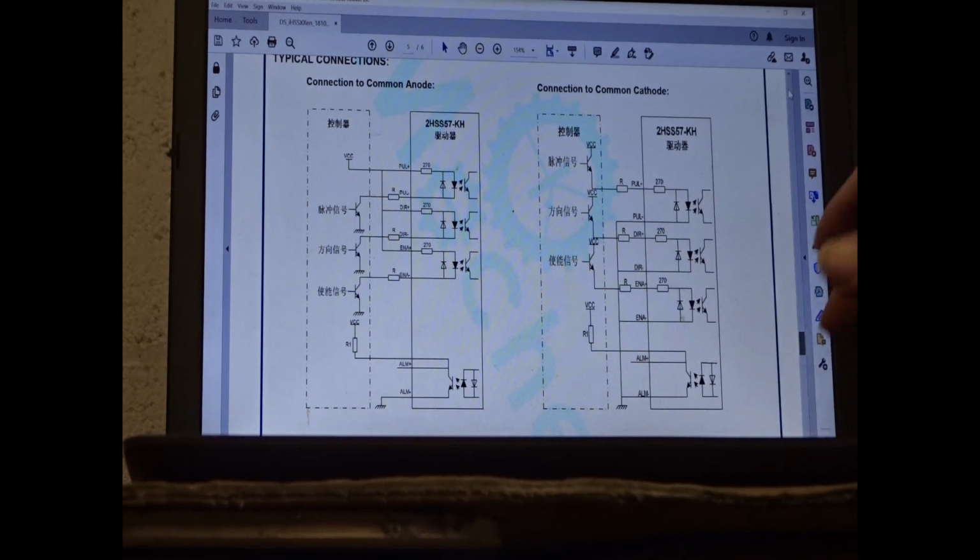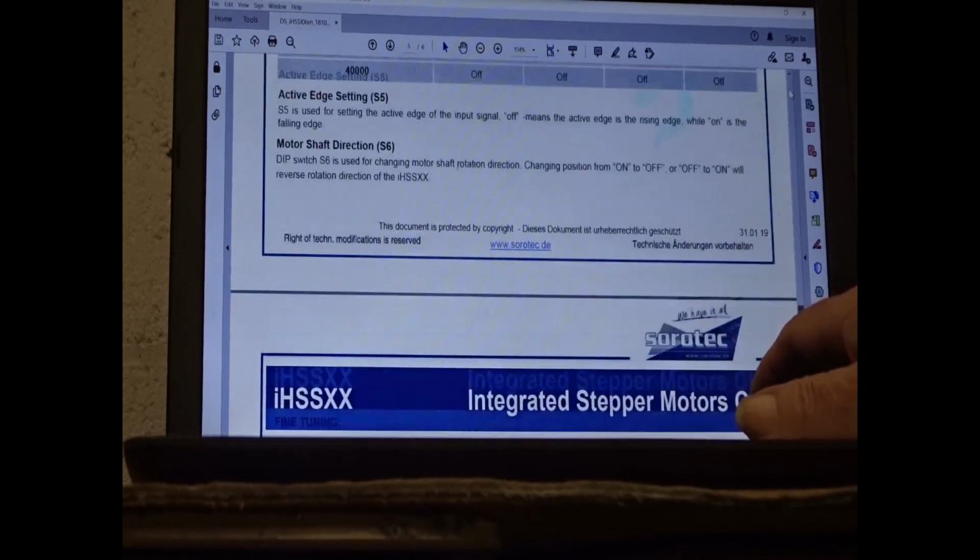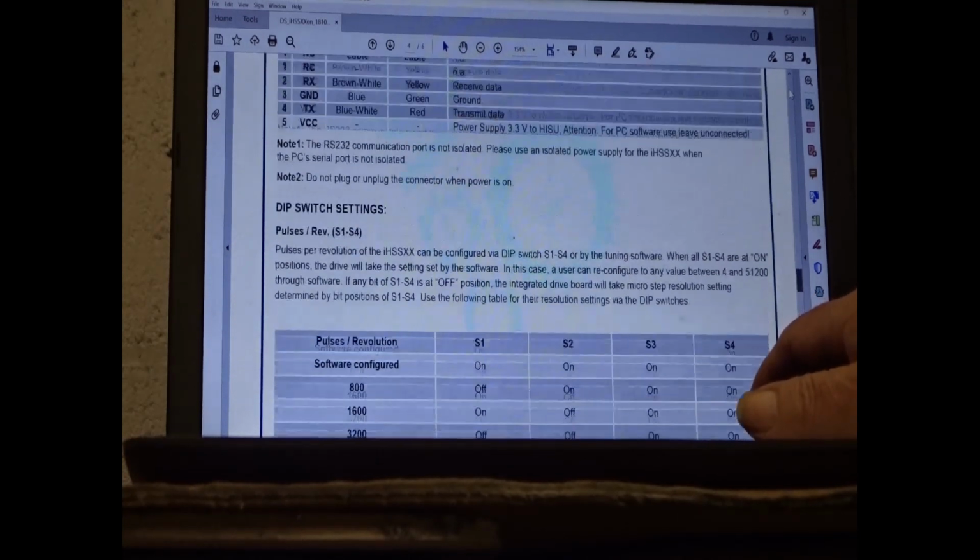Okay, that makes it harder to connect two inputs from a scope to different places. I can't have the ground connected to pull minus and connected to ground at the same time without screwing things up.